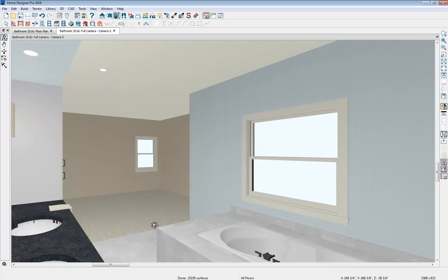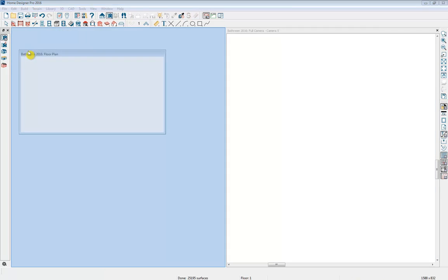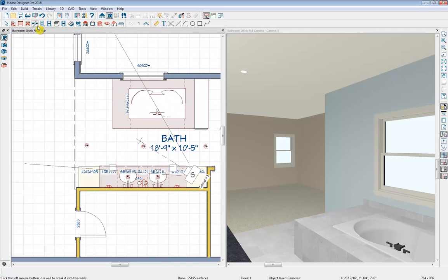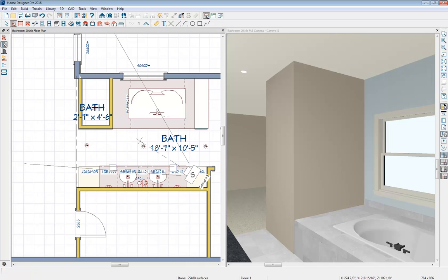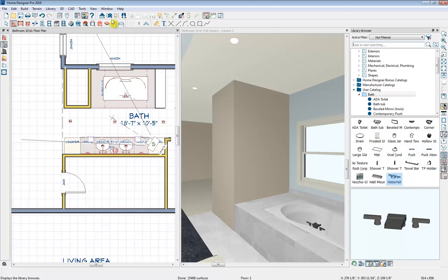Okay, so now we're going to use our wall tools, and I'll use just that straight interior wall, and we'll just click and drag that out. I do need to be pretty specific on this wall because I did find a double-sided fireplace in our library with a specific width, and then we'll continue working here. And again, I'm going to just delete that label. So now that we have our walls completed, let's drop in our fireplace.